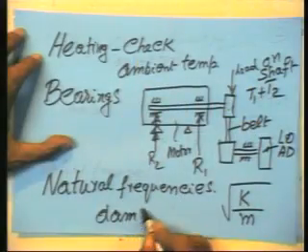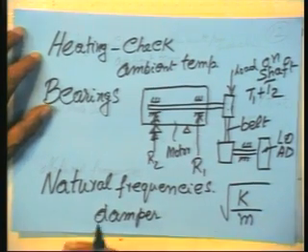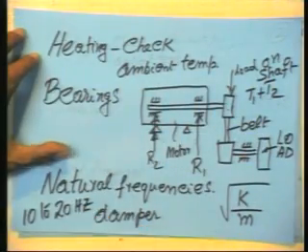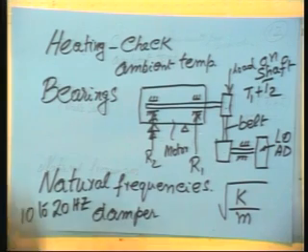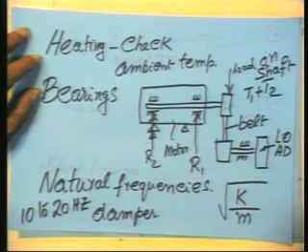You make sure that you operate the motor away from these natural frequencies, but if you have to go through those natural frequencies, you will have to provide a damper. Many a time that will happen. Typically the natural frequencies of the various drive elements and systems will be of the order of about 10 to 20 hertz, that is, cycles per second.